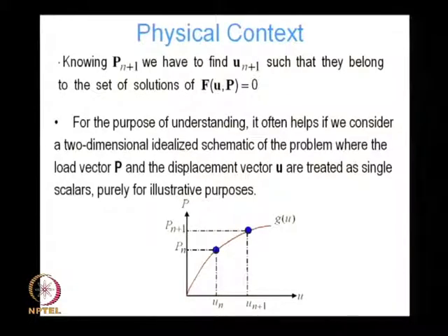And we decided to look at the nonlinear response of a structure which is in equilibrium due to the action of applied loads. And we said that the nonlinearity might be because of any reason, maybe because of geometric nonlinearity or maybe because of material nonlinearity. So, basically the problem becomes that we have to solve this nonlinear equation and we have to solve it incrementally. So, we have to decide what is driving the solution, what is my input and what is my output. The input in this case we decided is going to be our load vector.